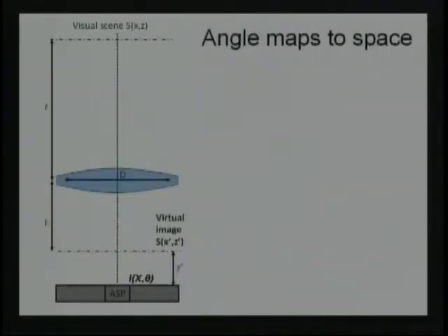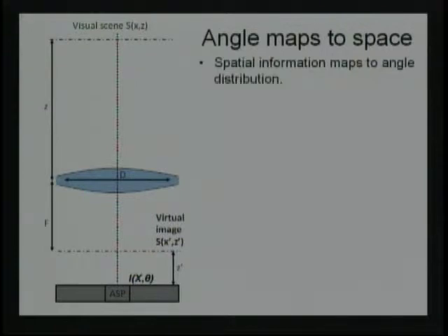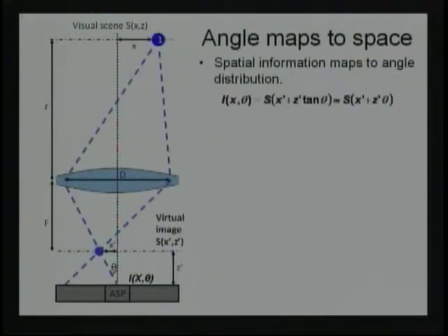Okay, so now a key piece to setting up that math and making this work is to notice that in these systems, angle and space map to each other. So for example, if I have an object at this location, and I'm out of focus, so it's brought into focus here, at this angle-sensitive pixel, that original offset in space maps to an angle offset at the pixel. And for different objects, we just basically get different angles. So any given pixel sitting in an out-of-focus image will be essentially mapping locations in space to locations in angle at that location over some range.